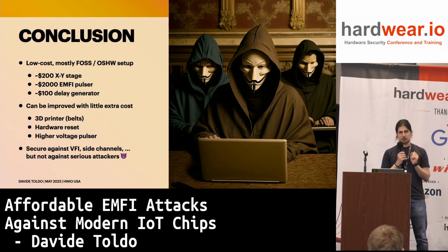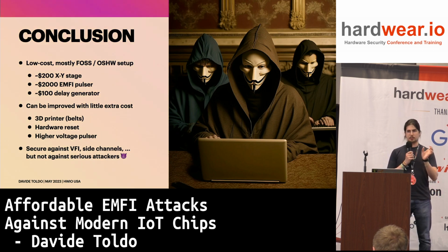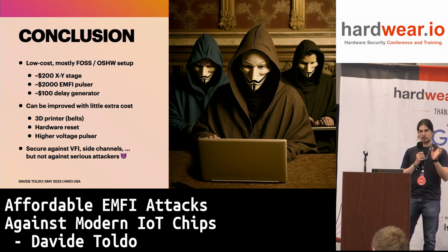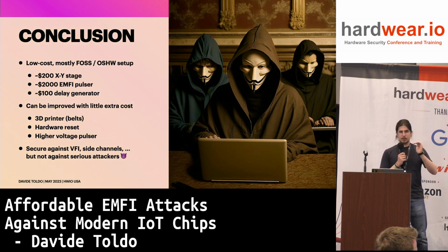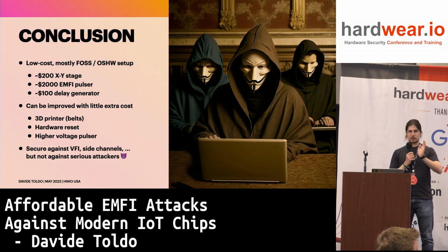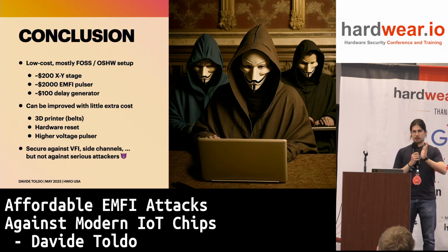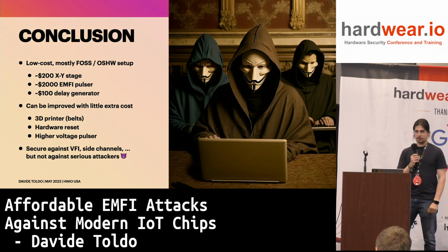You can also check out the power signature or EM side channels. For instance, if you are waiting for some crypto operation to happen on boot, you can see when it happens on your scope, and you can use that as a reference, and then you want to just go a bit earlier and then sweep a little bit in the time domain.